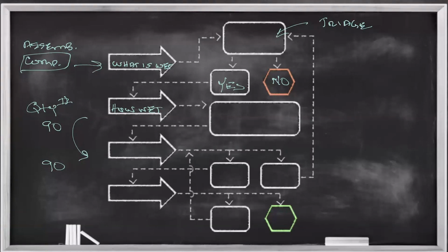And I think it's one of the things that we commonly do as an industry, as a habit, that we need to break: you have to have a quantification of how wet materials are on that first day. Now, once I know what is wet and I know how wet those materials are, then I can establish my drying plan.